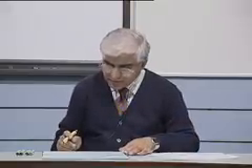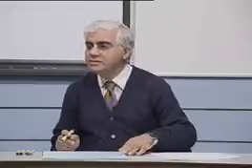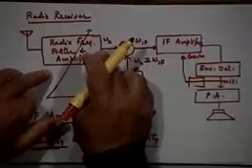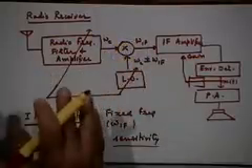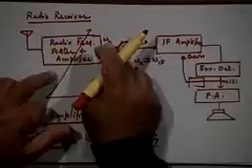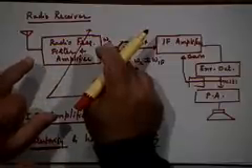So why can't we filter out omega c at the receiver, at the radio frequency stage? Sorry, why can't we filter out omega c at the receiver? So it will get filtered. No, you are absolutely right. So, the important point that you have made is the correct point. What we need to do is to make sure that while this filter may not be very selective, it should at least be selective enough so that while it is passing omega c, it does not pass omega c plus 2 omega IF.